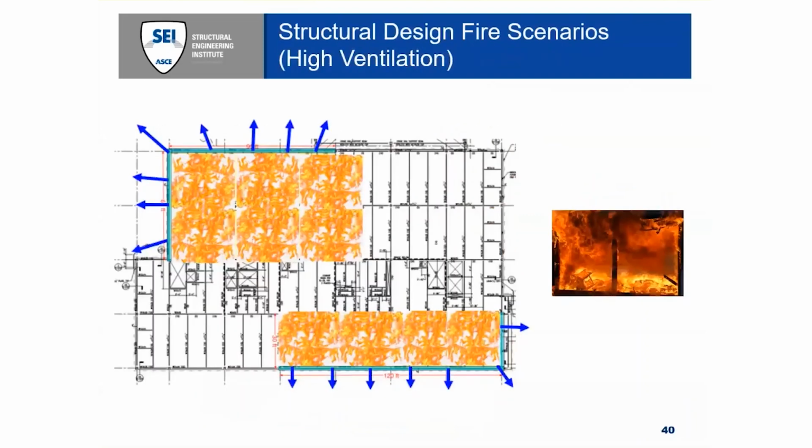Enclosure fires are primarily governed by the fuel load, the compartment geometry, and the ventilation openings. Since the final arrangement of interior walls may not be known initially or may change over time due to remodeling, we analyzed a number of conceivable compartment geometries and ventilation levels.